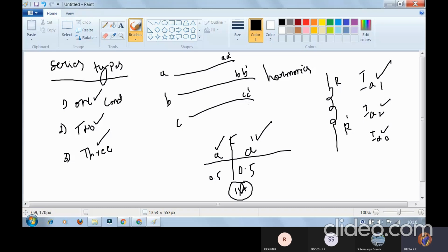Whenever we say the current exists, definitely the voltage should also act, right? You need to find two terminal quantities, one with respect to current and another with respect to voltage. The current we have written as IA1, IA2, IA0. The voltage should be calculated based on the fault condition. You consider a common current, meaning a variable current with different status: IA1 separate current, IA2 separate current, IA0 separate. But we assume voltage exists at every place with respect to the phases, one for each phase: VA A dash, VB B dash, VC C dash, meaning the terminal voltage across each part of the system.